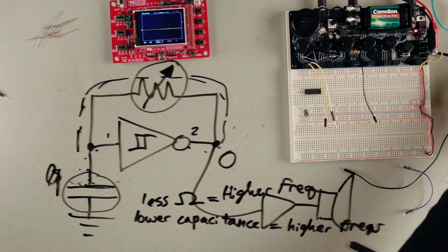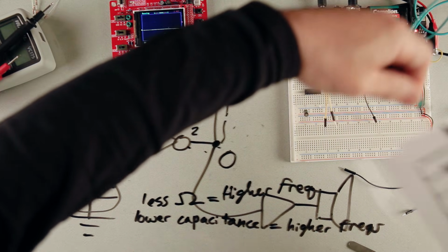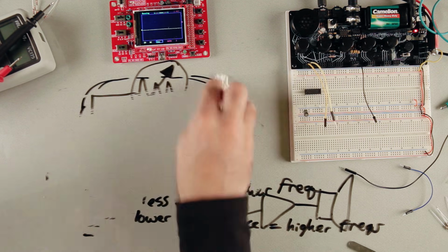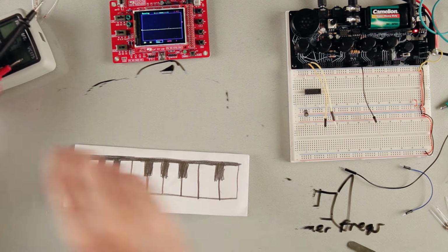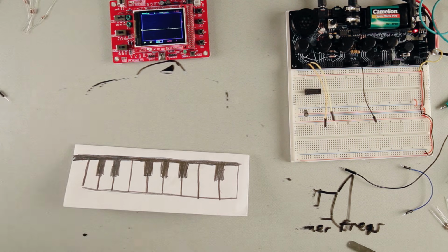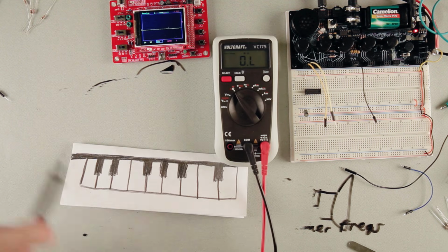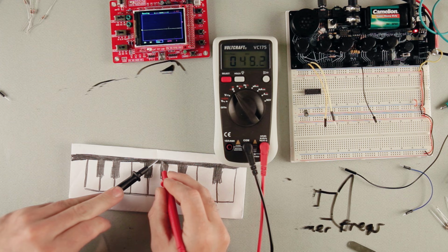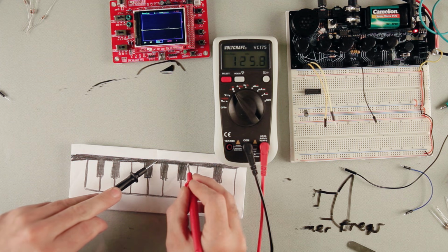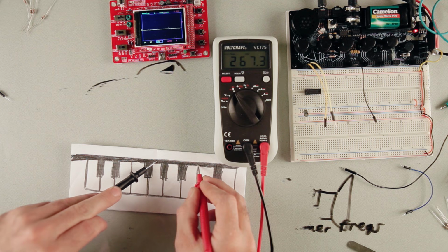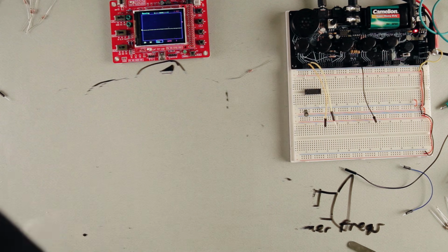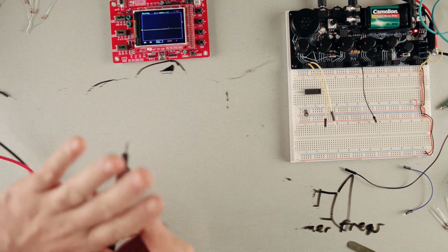But we can also get resistance with graphite on a piece of paper. That's another thing. So if we put our meter here, we can see now it's moving around a lot. Looks like 40,000. If I move it farther away, we're going to have more resistance. So now it's 250,000. And the other thing we're going to play with is a light sensor.